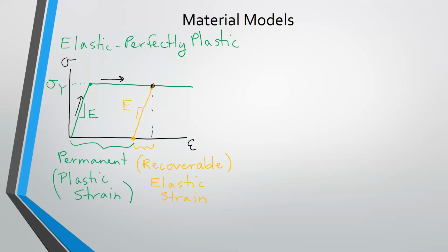Slightly interesting, it's permanent, but yet if you apply cyclic loading, so in particular, I'm thinking of bending. If you have a member that's, say, a cantilever, and you apply a load at the end and you bend it and you get it to go into its plastic region, and then you unload it, it's going to have a deformed shape. So it's going to end up kind of trailing down.